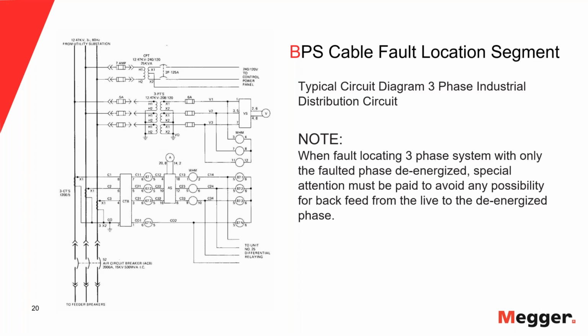Whenever we do fault locating in three-phase systems, we have to pay close attention to make sure that when we fault locate on one of the phases, the other two phases, if they are energized, don't backfeed unknowingly somewhere into the phase that we want to fault locate. So there has to be some checking done to make sure that if there are any backfeed points, they are open.